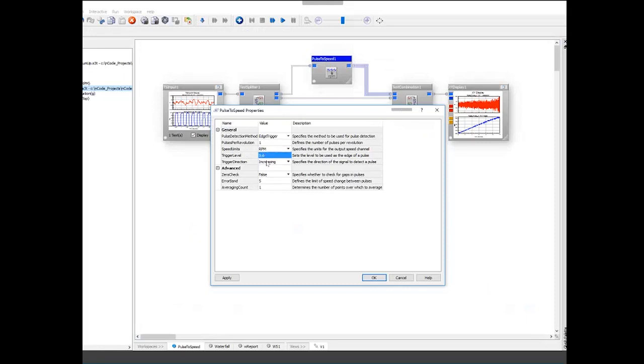And therefore the delta time will be calculated between each pulse. The output units is RPM, and I've got, say, 1 pulse per revolution. So now what I can do to improve this noisy RPM signal is just to perform a running average on the signal. So say every 3 points, I'm performing a running average filter over this signal, and every 3 points it averages.